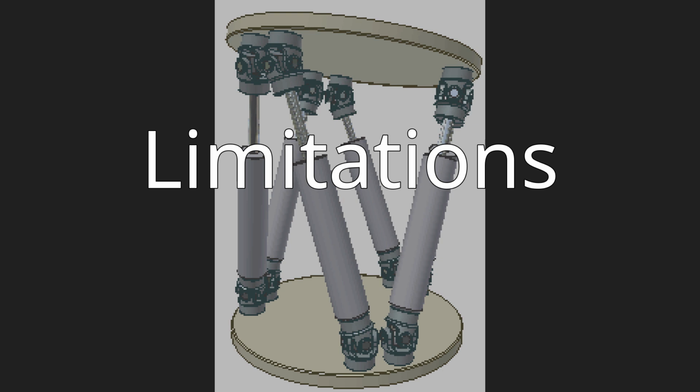Tilt coordination angular acceleration: this false cue is caused by the angular acceleration generated by the tilt coordination occurring about a point other than the pilot's head. The angular acceleration combined with the moment arm from the center of rotation to the pilot's head results in the specific force false cue at the pilot's head. The point about which angular rotations are simulated, the so-called reference point, is typically at the centroid of the upper bearing block frame for hexapod motion systems.